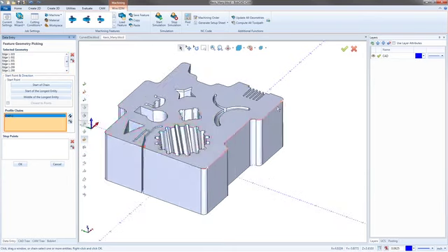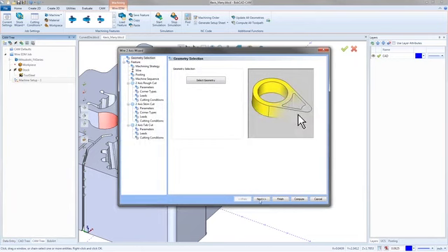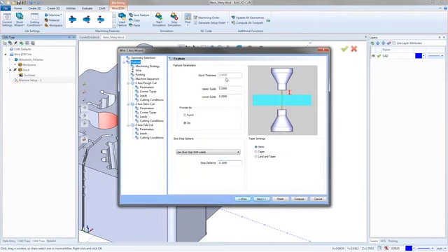So let's go right there. I want it to comp left, so that looks like the direction I'd want to cut in. And so we'll go ahead and hit OK. Next, we can then set up the stock thickness. It's already there from when we set up the stock. The upper and lower guide locations are not something that every machine needs output, but some machines do output the guide locations as opposed to the wire location. So this would be actually where the position above the part is that the guide's sitting. You'll have code come out based on that.